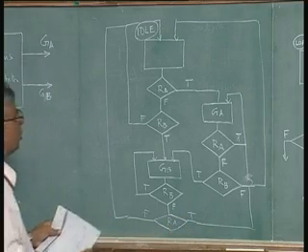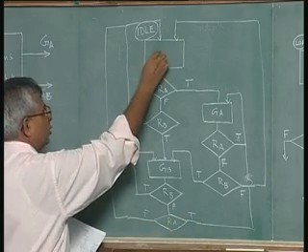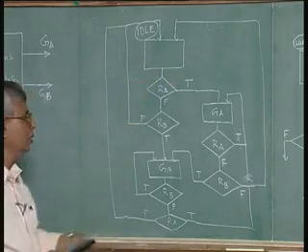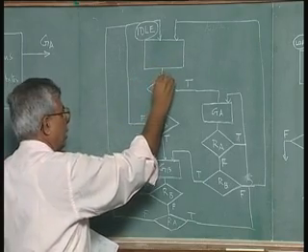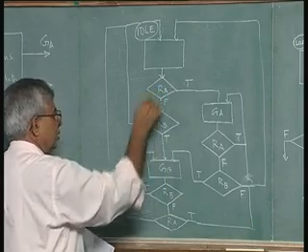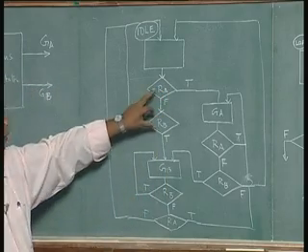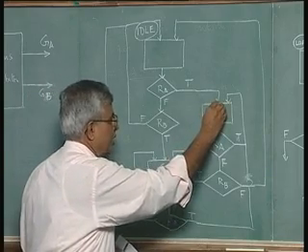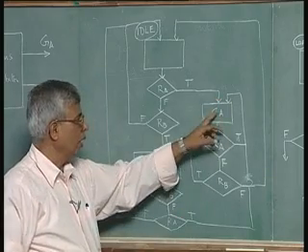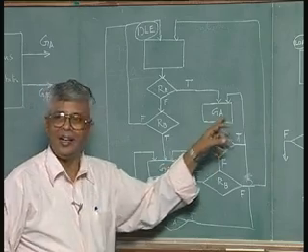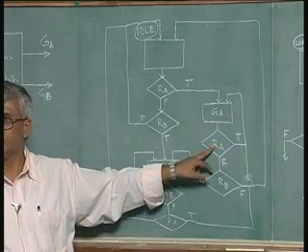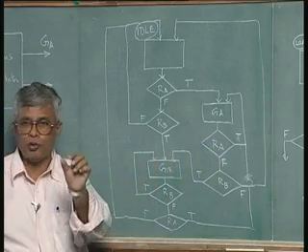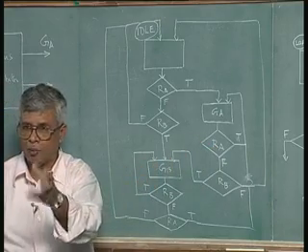So, this ASM is very simple. There is an idle state, there is no output inside; I have not put any output in the box, and you keep checking RA and RB in the same clock cycle. If RA is true, the next clock cycle you issue GA, and keep issuing GA as long as RA is kept high. That is why I put one more RA here, because I do not want to issue for just one clock cycle when RA has not removed the request.